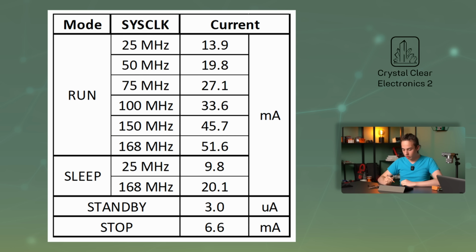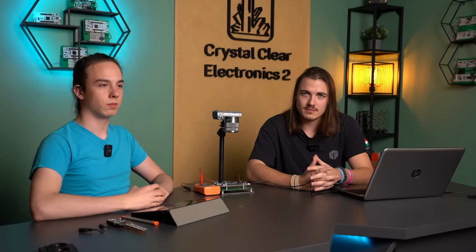In sleep mode, only the processor's clock is turned off, the peripherals remain active, and continue to consume power. The measurement also shows higher power consumption at 168 MHz. As you make these measurements at home, you will get slightly different consumption values. This should not be surprising, as the actual power consumption depends on many things, such as the ambient temperature and thus the temperature of the microcontroller core.